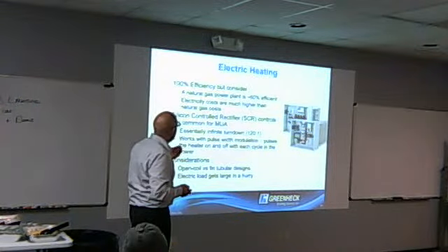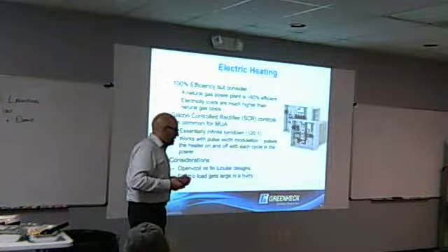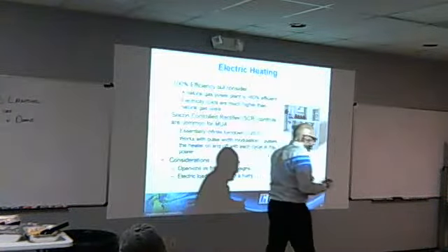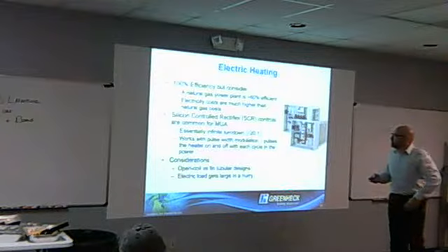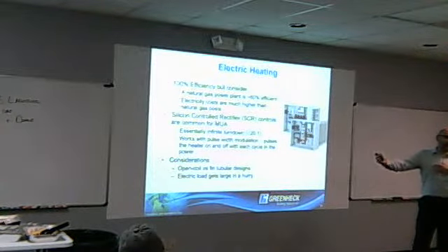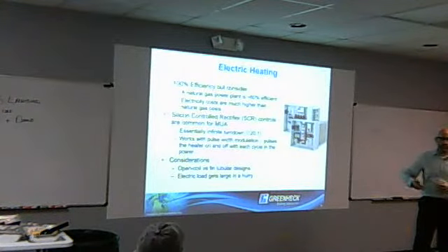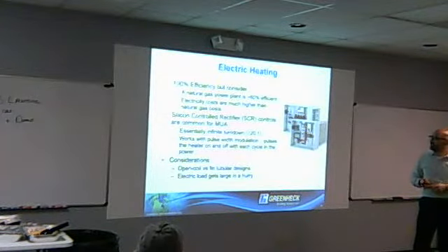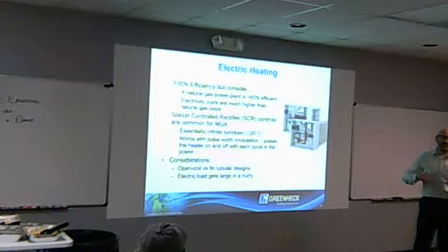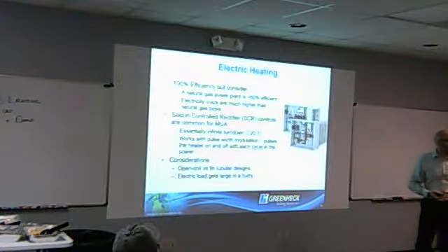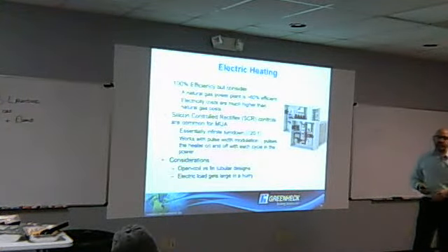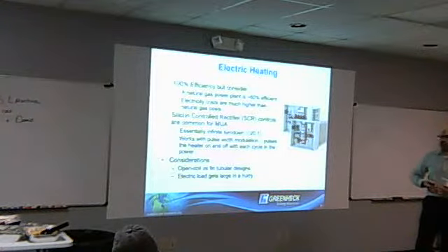In terms of electric heat, it is 100% efficient. The energy you put into that coil is going to come out, but don't forget, we are generating that electricity, probably inefficiently, back at the plant. By the time it comes out your outlet, it's less than 20%, right, for the line losses and everything else. So there's the buzzword now, electrification, decarbonization, and this idea of moving to all-electric buildings. I think New York has implemented a rule that you shall not have any new gas-fired appliances installed.